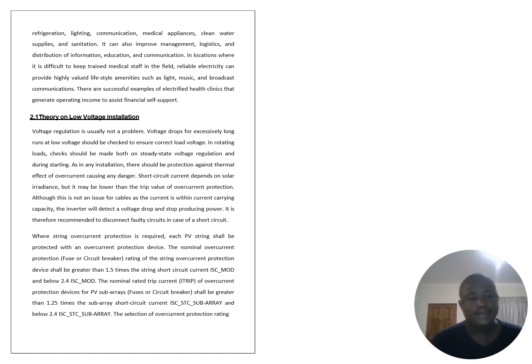Nominal current protection fuses or breakers rating for string overcurrent: the device shall be greater than 1.5 times the string short circuit current, ISC_MOD, and below 2.4 times ISC_MOD.